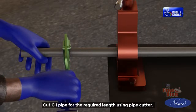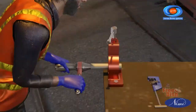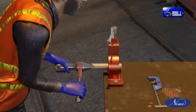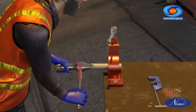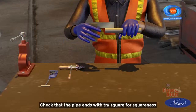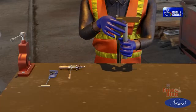Cut GI pipe for the required length using pipe cutter. Remove burrs using pipe reamer. Check the pipe ends with tri-square for squareness.